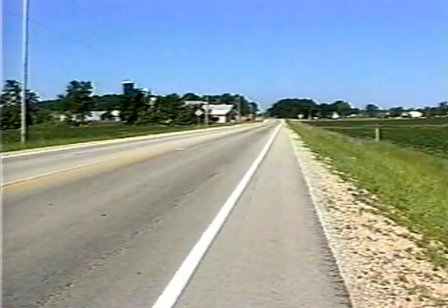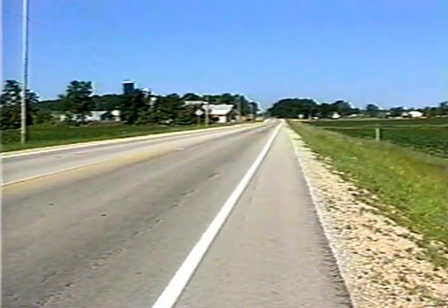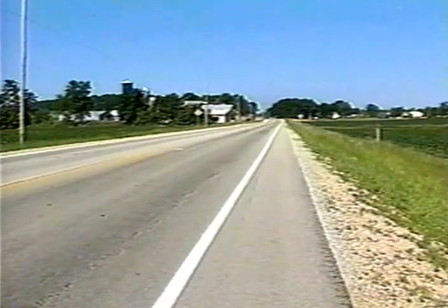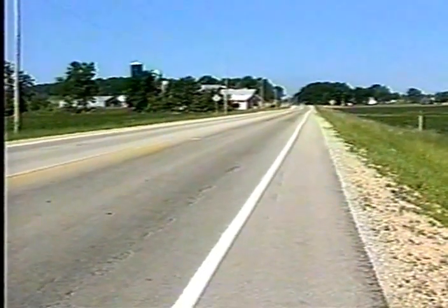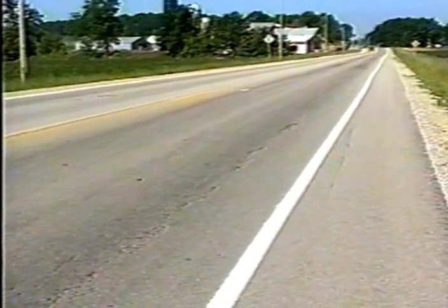This ought to be an indication to you that perhaps the maintenance technique or the repair technique selected was not the most appropriate. And if we look at a second case, now here the cracking is not nearly as extensive. You see just a hairline crack in the outer wheel path. But this is a brand new asphalt surface, and when you see hairline cracks developing the next year in your overlays, you know that you probably covered up something that demanded more extensive repair than simply putting an overlay over what was probably wide and raveled crack patterns.